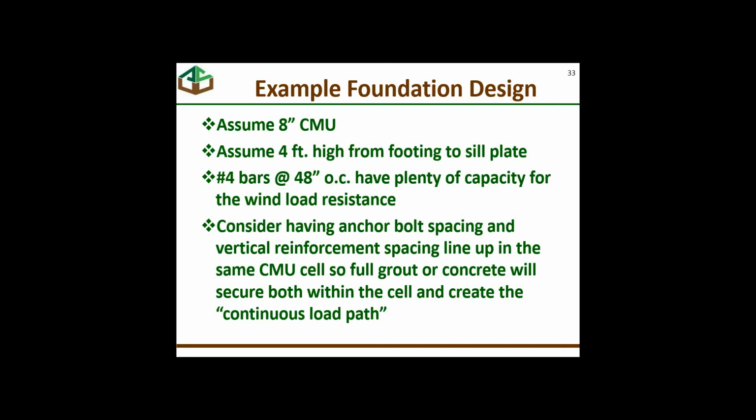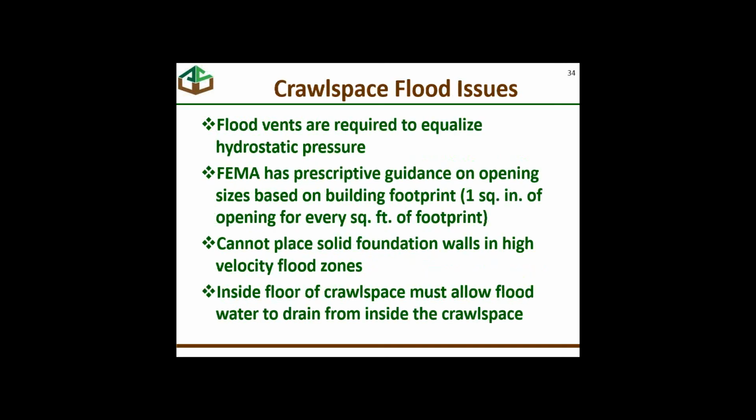I certainly would consider having the anchor bolt spacing and the vertical reinforcement all line up in the same cell so that when you grout or concrete in the cells with the anchor bolts, we've got a continuous load path through from sill plate down to foundation, down to footing.